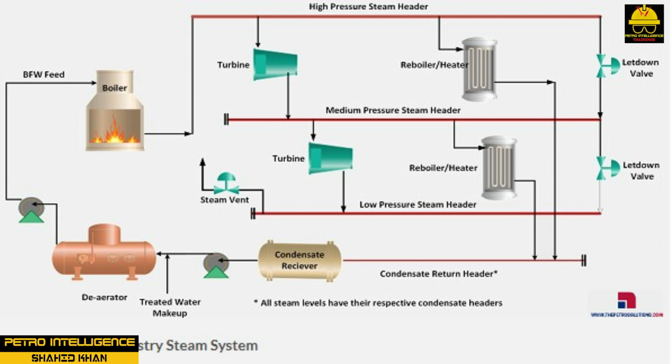Extraction steam and imported steam flows are regulated to maintain the header pressure at 400 to 800 psig. The pressure of the imported steam supplied through a pressure control valve is slightly higher than HP header pressure. In order to maintain pressure and steam balance in the medium pressure steam header, a letdown station is provided between the HP steam header and MP steam header.